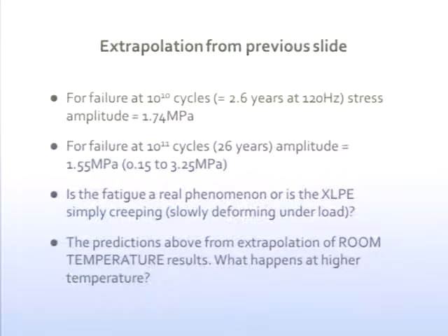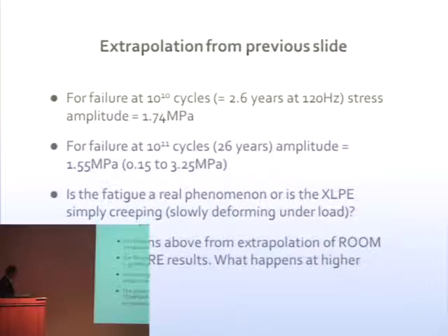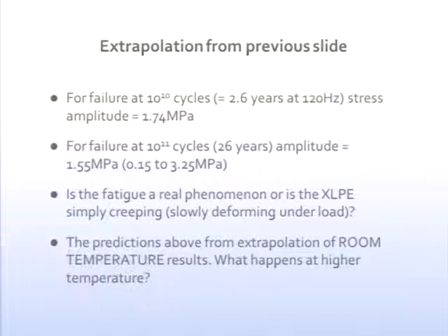And at 120 hertz, that's 2.6 years. And the stress amplitude you need for that is 1.74 megapascals. If it's 10 to the 11 cycles, that's 26 years. This begins to sound like the lifetime of a cable. The stress amplitude is 1.5 megapascals. Let me stress what I mean by this. Dreadful pun. That's actually taking the stress point from 0.15 megapascals to 3.25 megapascals.